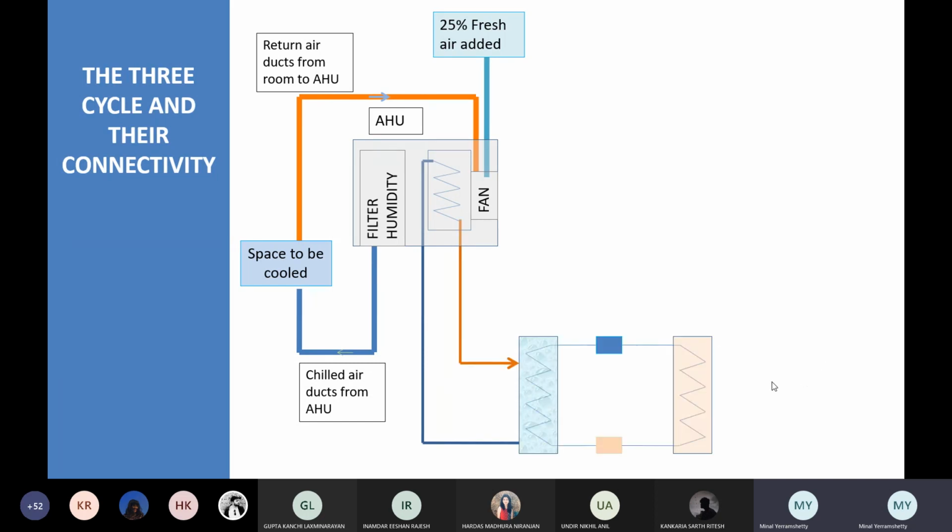Okay. Let me go to this. Okay. See what happens. So this is my evaporator where it is shown. It's blue in color. That means chilling happens here. Okay. So from here, what happens is, because this chilled water has happened, you remember the physics behind this, right? Now this refrigerant has turned into gas. Now when something turns into gas, it needs heat. For evaporation you need heat. If I'm having water and I'm boiling it, only then it turns to vapor, right?